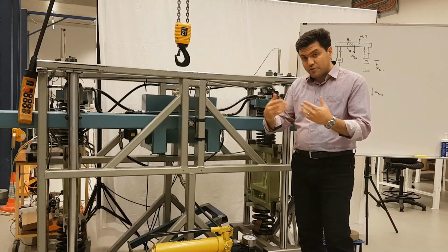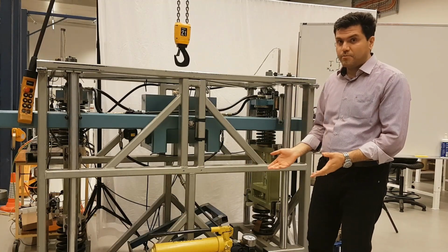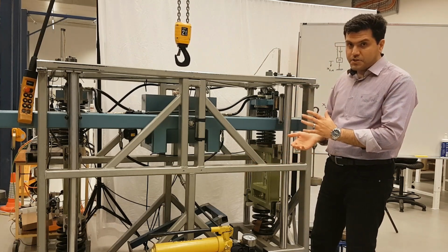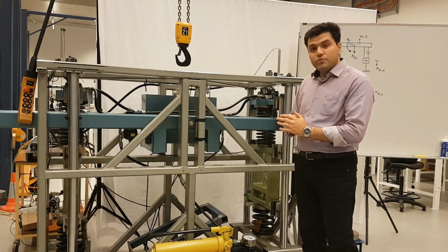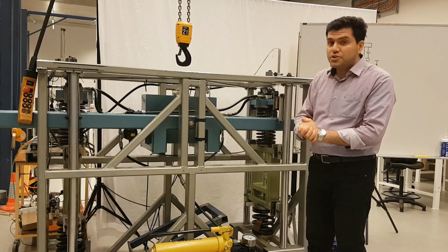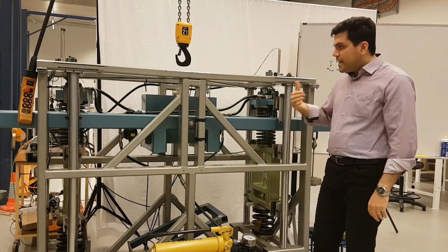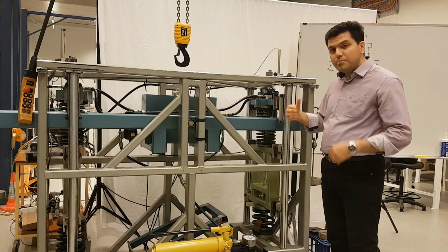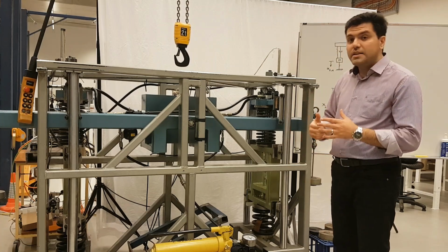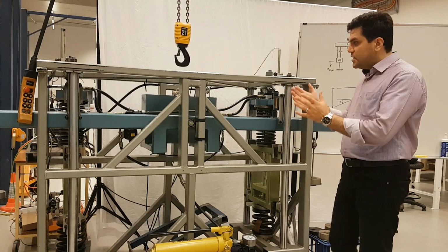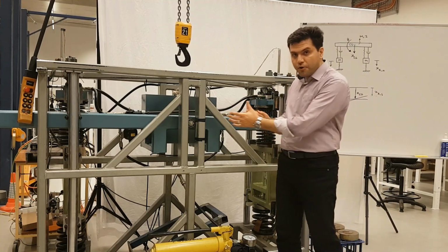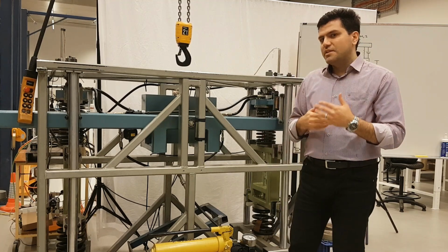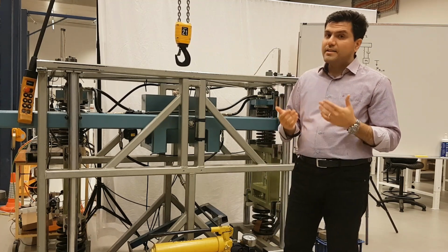We do have an interconnected hydraulic suspension system. This system offers more advantages with respect to conventional suspension systems. It mainly affects the stiffness and the damping coefficient of roll mode relative to bounce mode. Because of the arrangement of the housing here, once you apply the pressure, it will change the stiffness of the roll mode rather than bounce mode.